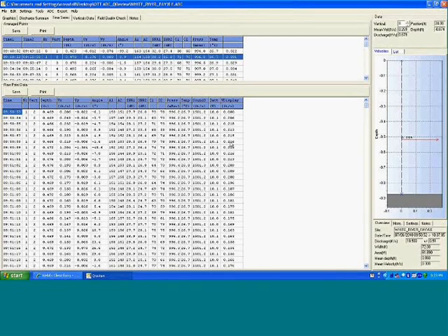In the lower graph, the 1-second time series measurements or raw measurements from the ADC are shown. There's additional information in these 1-second measurements that is not shown in the verticals data that we just reviewed. For example, when we look at signal to noise, correlation, and signal amplitude, I see the values from both beam 1 and beam 2, whereas in the verticals data, it was an average of both, and it was an average over the measurement interval.